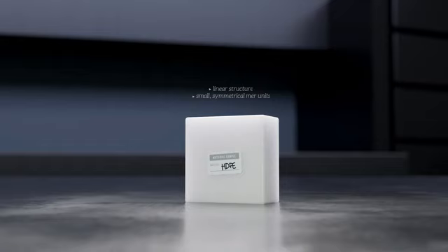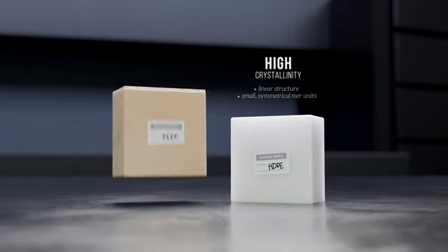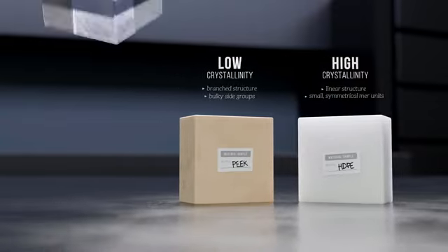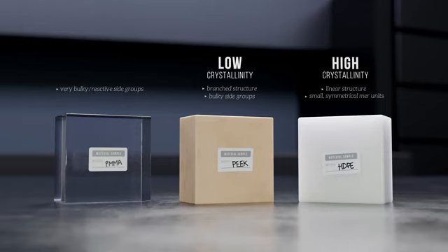Linear polymers with small symmetric mers tend to have the highest degree of crystallinity because these characteristics allow chains to pack together very closely. Branched polymers, or those with other features that prevent close packing, like bulky side groups or irregular mers, tend to be much less crystalline. And some polymers that have very bulky or reactive side groups are completely amorphous, because the side groups completely prevent polymer chains from arranging themselves into an ordered structure. This is also true of cross-linked polymers, because cross-linking prevents polymer chains from forming ordered structures.